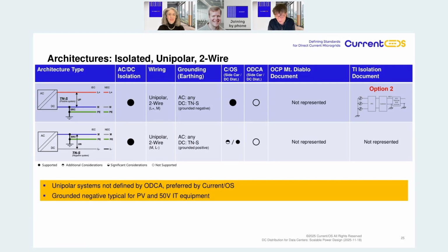And think about it in OCP, because you want to do immersed cooling, you have a lot of earthing arrangements to do, you have a lot of piping, so stray currents can be quite dangerous because they could have an effect on the equipment. And the architecture with the positive system is the one that has the lowest amount of drawback from these kinds of effects.